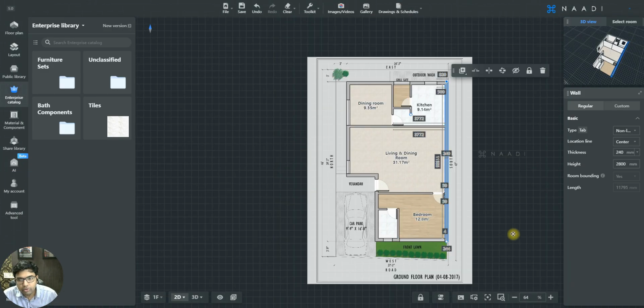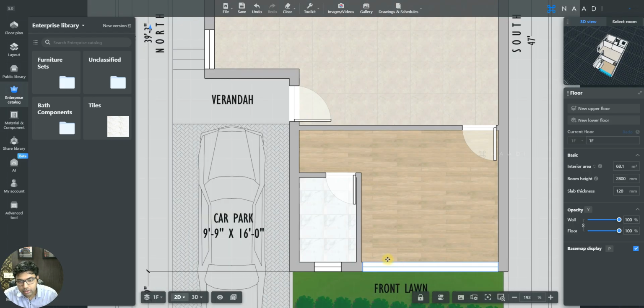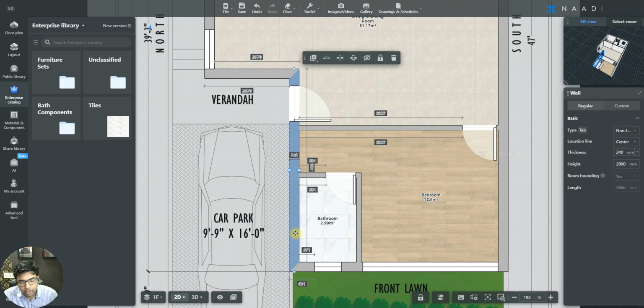Okay, so this should be your second inspection, adjusting the length of the wall. The third inspection is checking the thickness of the wall here. So click on any wall and on the right it will show you its respective parameters. Like I said, this is the parameter window, right? If you click on any component, it will show you the parameters of the component. That way I'm selecting a wall. On the right-hand side it is showing you the parameters of the wall.